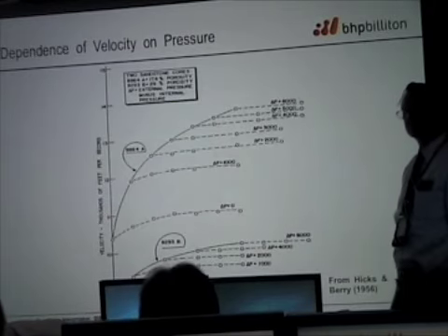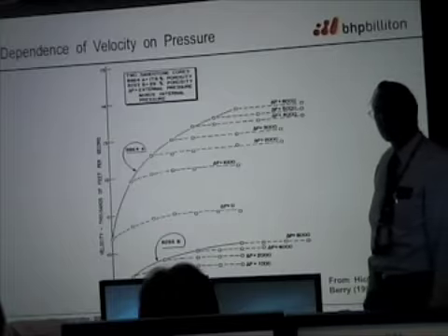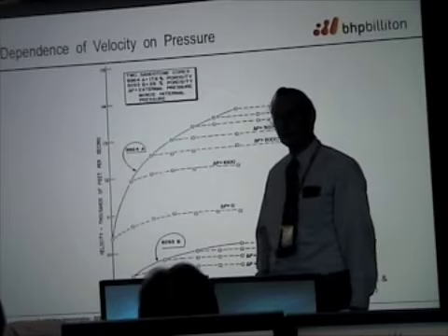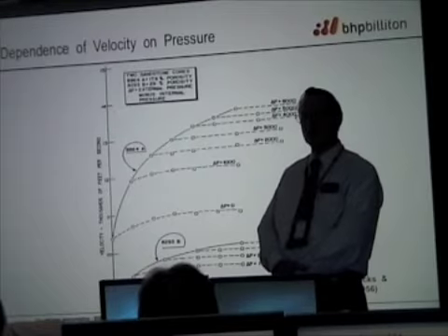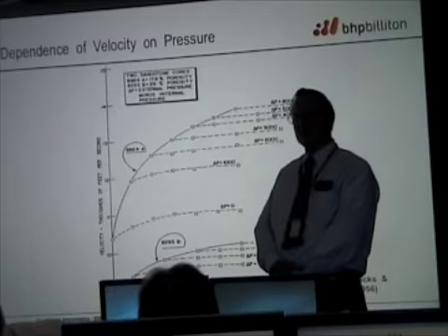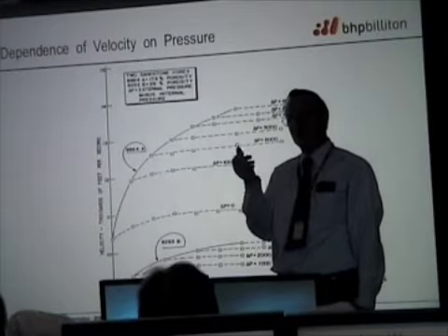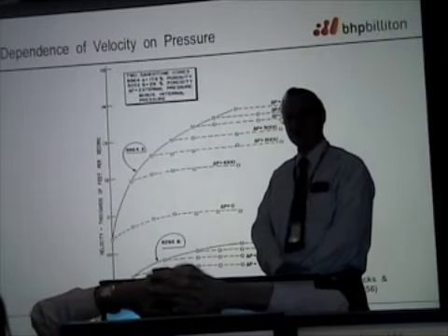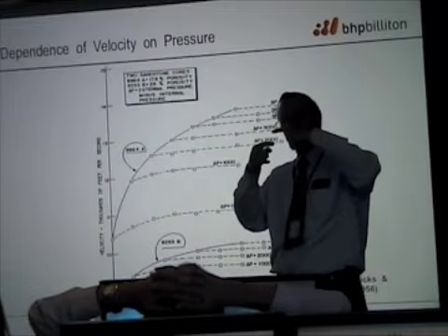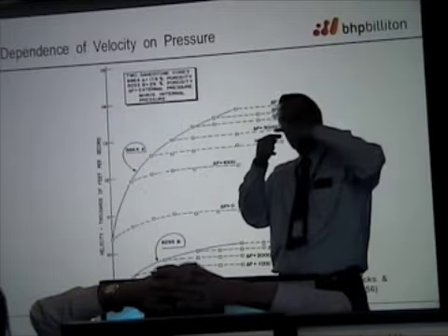How do you maintain the pore pressure? I can see if you press a sample, that's a confining pressure. But the pore pressure, like pumping water into the rock. All right, here's how you do it. You machine some, say, stainless steel heads to which you attach with cement the transducers.